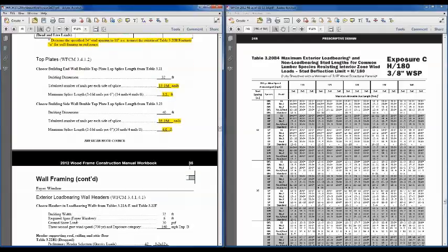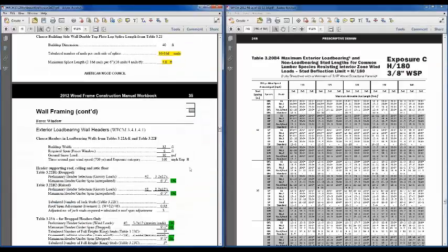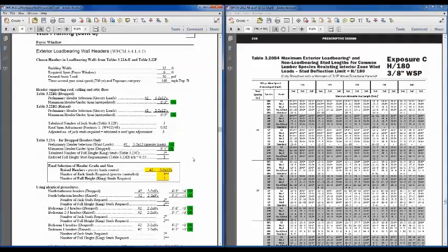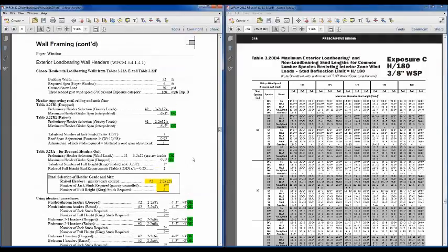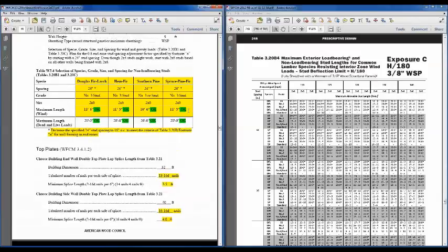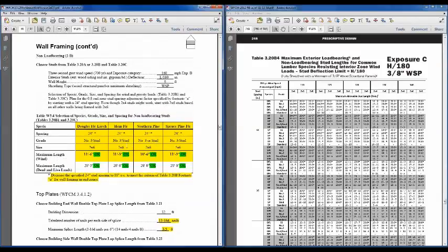Yes, go ahead. I have a question that came in. Great. Someone mentioned that in their part of the country, reduced stud spacing at the end zone is rarely used. Are there any tables that incorporate the 0.8 reduction factor? Yeah, so I probably glossed over it a little too quickly, but that 0.8 should actually be worked into your design ahead of time.